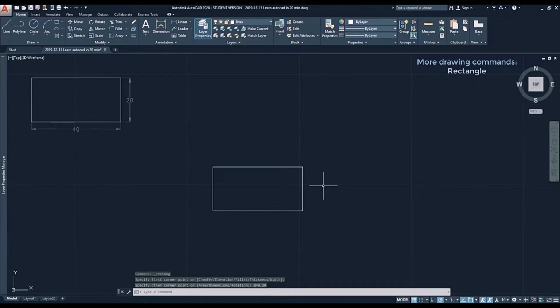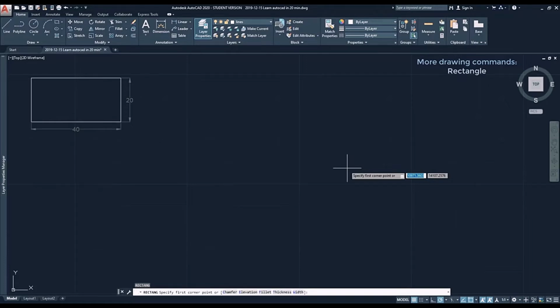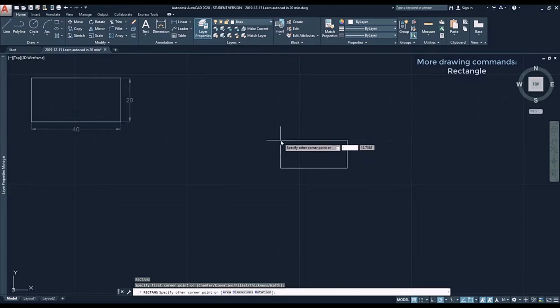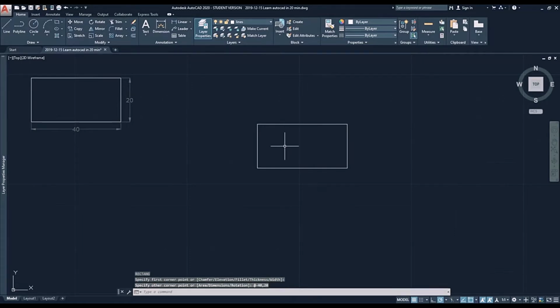However, as I still have to take into consideration the UCS coordinates, sometimes the values might be negative. Let's suppose I draw another rectangle but with the start point. The x-coordinates would be -40. Click for the start point, then type -40, press tab, and as the y-coordinates are positive, I type 20. Here you have the result.